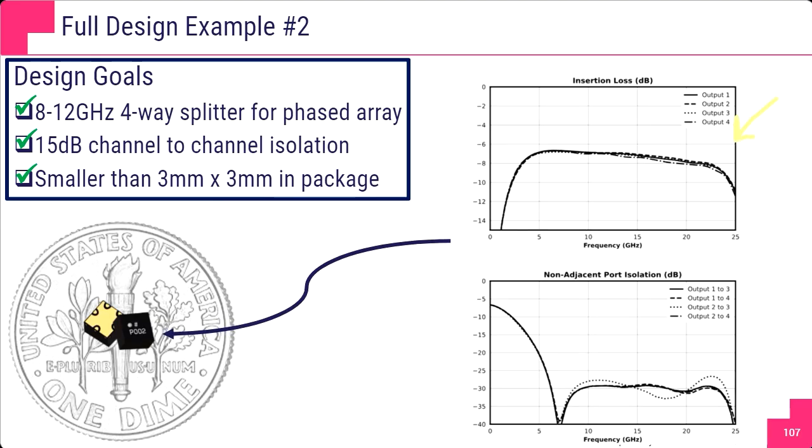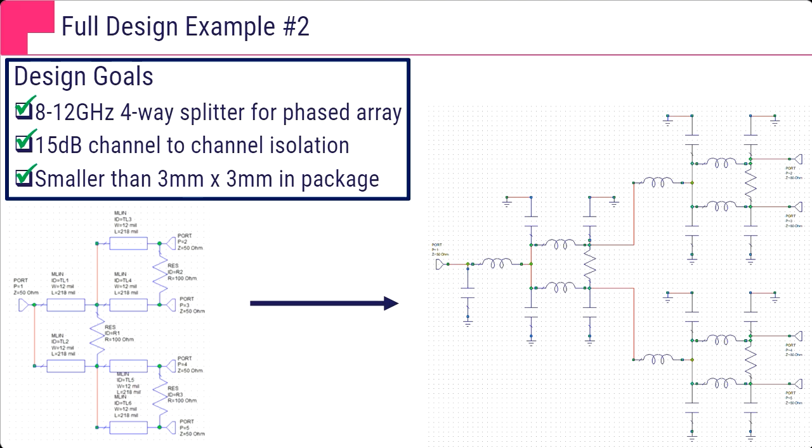All of the other Wilkinsons, I was going to just show the other Wilkinson divider that we showed looked more like this. Goes all the way down to DC. So why does this one not go all the way down to DC? I alluded to it here in this slide. This equivalent circuit, it's equivalent to what we're looking at here, in that there's a transmission line, there's your isolation resistor. But this is not exactly what we're implementing inside of the CSP.